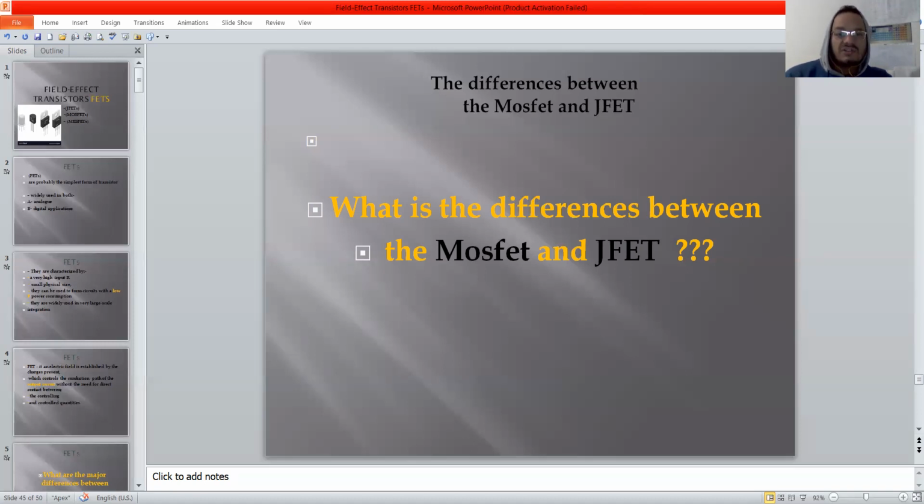As the drain source voltage increases and approaches the pinch off voltage, the depletion region will be widened and cause a noticeable reduction in the channel. That means the channel width will be smaller. Yes, from this side, at the right side. The drain source voltage is increased from 0 to a few volts.